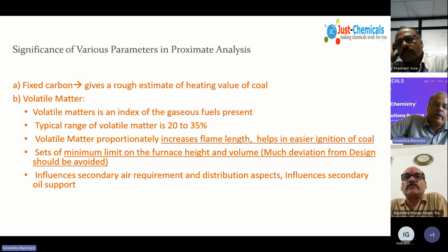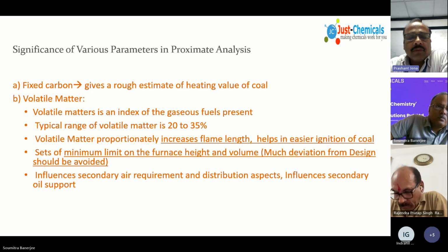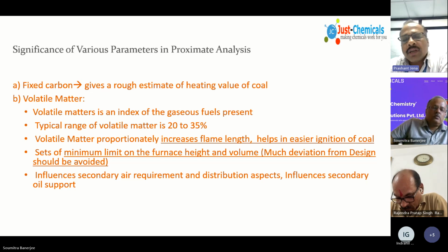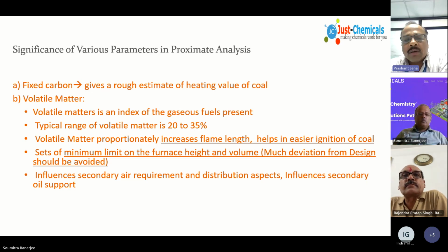You may try increasing secondary air, but normally in CFBC boilers secondary air is avoided, since secondary air provision is already given. But in AFBC boilers, normally these old boilers of about 10 years and past, they don't have secondary air provisions. So at NIRA, we are facing this challenge of high unburned carbon, and we are using imported coal which has volatile matter between 30 to 35 percent.